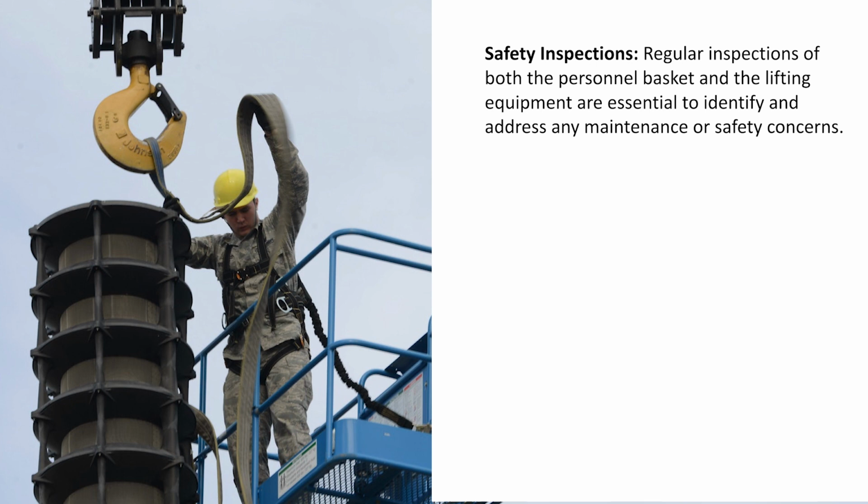Fall protection. Workers inside the basket must wear appropriate fall protection gear, including safety harnesses and lanyards. These should be properly attached to anchor points within the basket. Safety inspection.